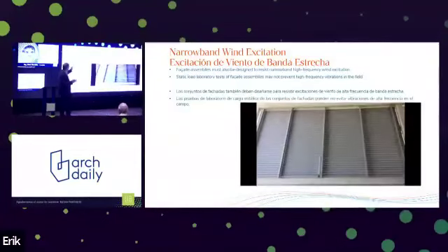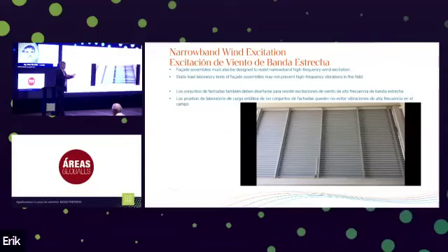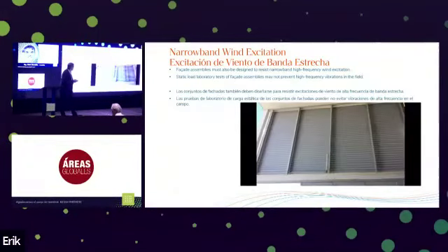Unfortunately, static load laboratory tests of facade assemblies may not prevent this high frequency vibration in the field. We're traditionally testing with static load tests, sandbag tests, for example, and they can miss this phenomenon.